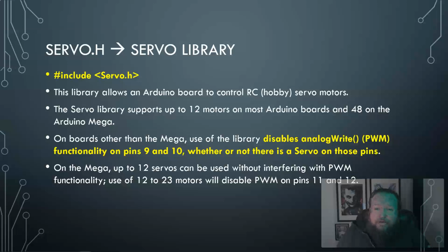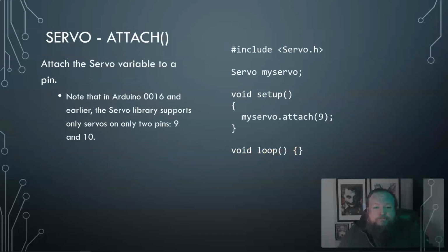Generally at most you're going to have like 2 servos directly connected to Arduino. Anything beyond that for the micro ones, I suggest having a separate power source. So connect them to pins 9 and 10, and then for the rest of your project, any other sensors you're connecting, you cannot use 9 and 10 to do analog writes if you want to control them. So no more fading lights on 9 and 10, but any other PWM pins, you're good to go. So, fun parts, but this takes some of that research of, again, limitations and weird things that then pop up.